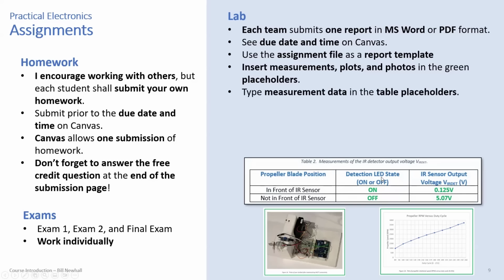Right? So that's the purpose behind collecting all this data and these plots. It's not just busy work. It's actually to have data so that when we move forward and integrate with the battery, the DC to DC converter, the motor, and the microcontroller, when something's not working, we can take individual measurements of those components and check them against your data.